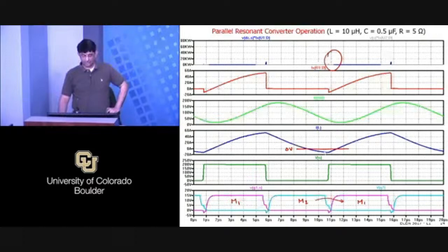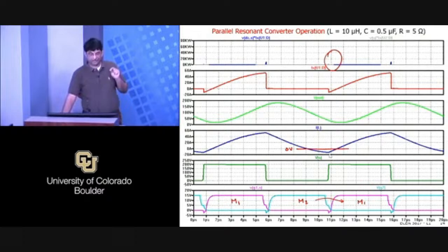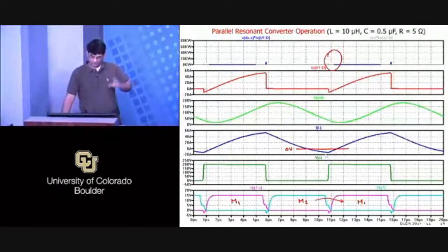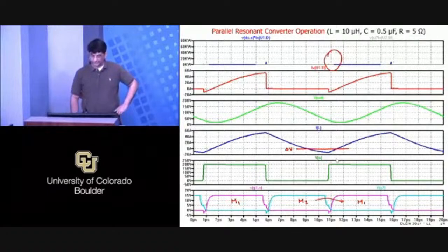The fundamental thing here was that the current was negative. What you really have to have is enough energy in that inductor to be able to charge and discharge those capacitors. So it's not just that it's negative, it needs to be negative enough that there is enough energy in that half L i squared to charge and discharge those capacitors. We'll look at that more carefully later.